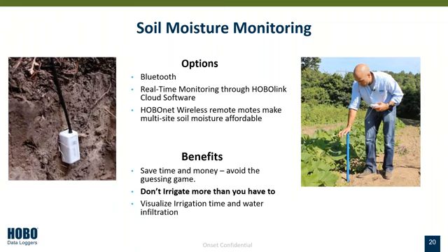And one thing that I like to do with my customers and with people I've worked with in the past is dig down, install that sensor, put it in, cover everything up. And then once you get your data and you can see that data point, it's going to give you a data point on how much water is available in your soil and what the water content is like in your soil. So if you go down, say a couple of feet away from where that sensor is, I recommend digging down to the same depth. Say you put a sensor in at 12 inches.